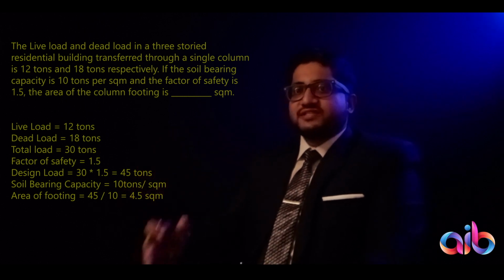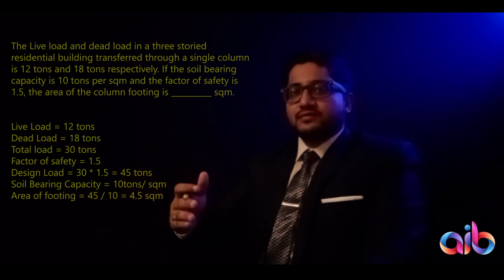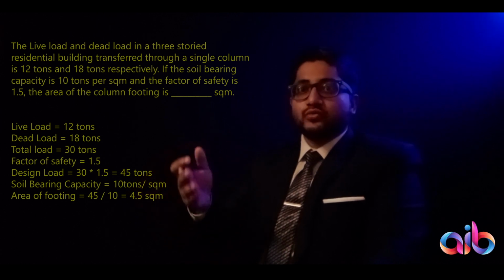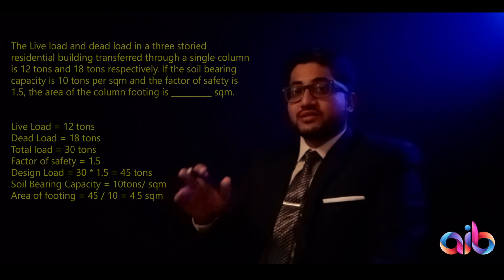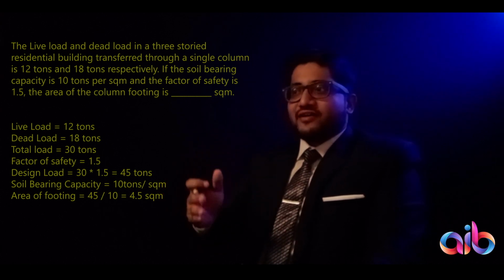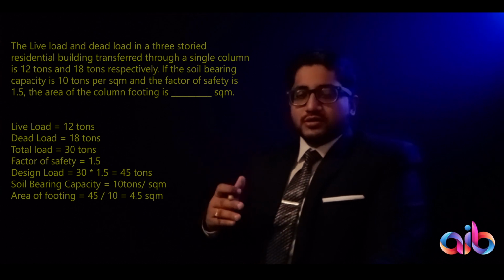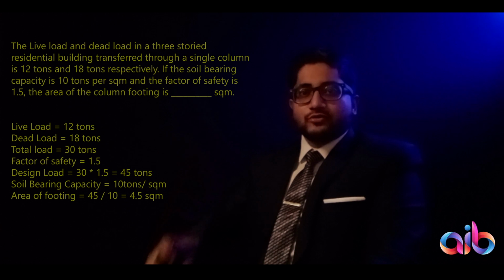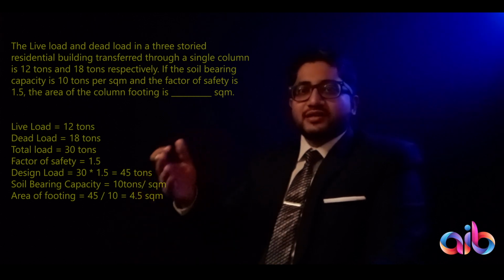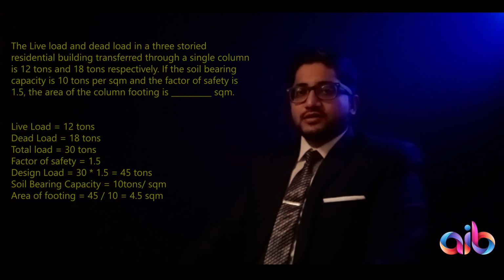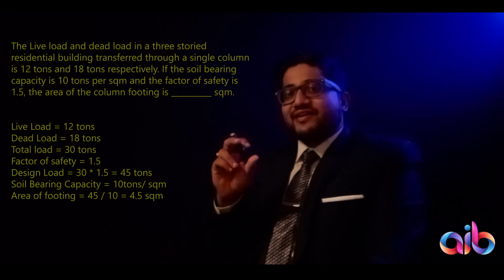So if I have designed the building sufficiently well to counter the load imposed by its self weight with you inside of it, that's fine. But the day 50 people get inside your building, if I have not taken extra caution to account for that extra imposition of load, maybe on that fine day the building will collapse, killing all 50 inhabitants then and there. So that is why you should always take a factor of safety.